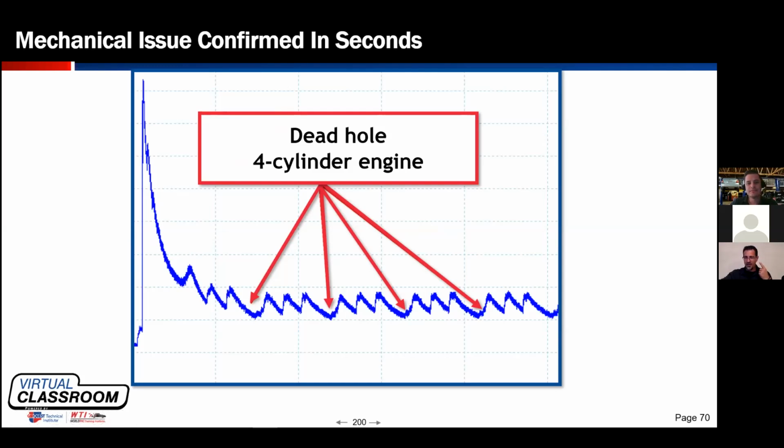What you hear with your ears is a change in crankshaft speed because the load from one of the pistons goes away. I shouldn't say goes away. There's always a little bit of load, but it's far less than a cylinder that has integrity. So we've got one starter, we're going to call it a starter hump, a good one that reflects the same or a very similar value, a third one, and then look here, one's missing. So like Brent said, we've got da-da-da-da, da-da-da-da, that repetitive sound.